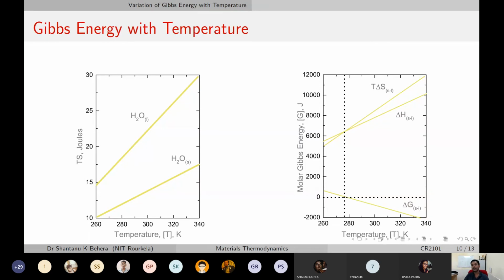So what we have here is from the S curves or both of the Ts curves, we find out T delta S curve for the solid and liquid transition, and for the two H curves we find out the del H curve for solid to liquid transition. Right. So how do you do this T del S curve? This T is constant. It keeps on multiplying with this. If you calculate the T del S, that is T into del S liquid minus del S solid, and you calculate that for every temperature and multiply that with temperature, which is what is going to give you this kind of curve. That is a T del S solid to liquid.